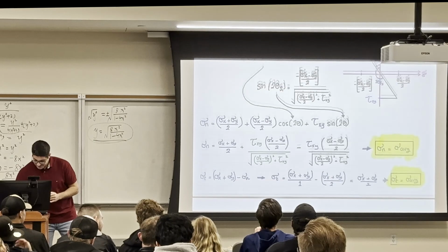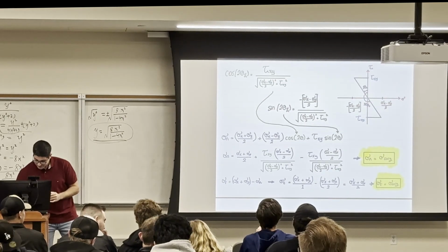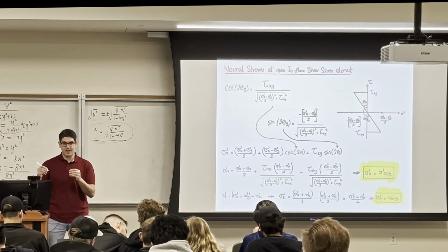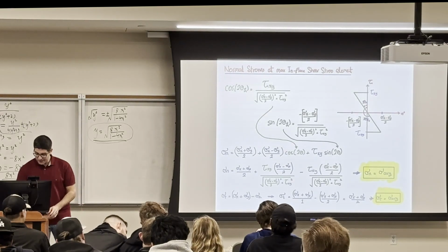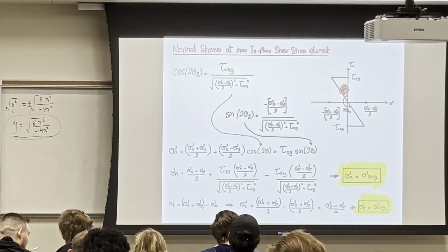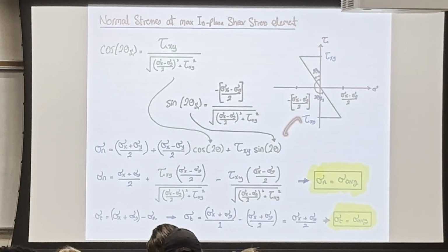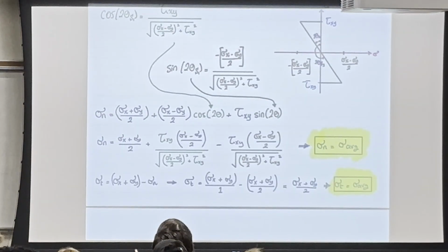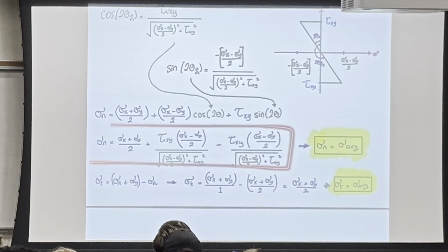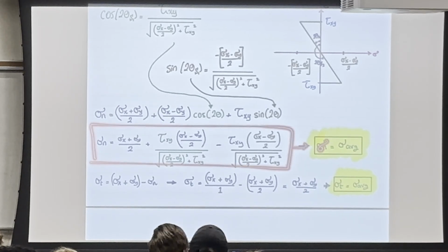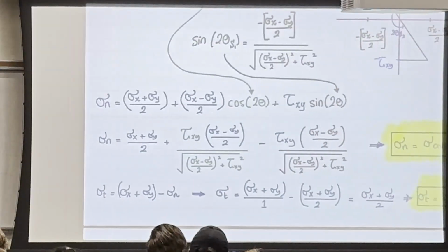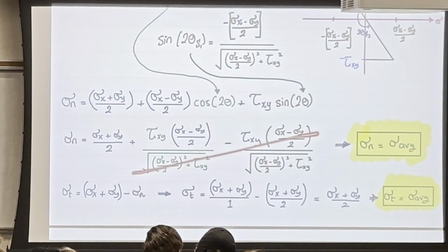So here, I just took the theta, and instead of substituting the theta, because I want to generalize this, I took the cosine of the theta s and substituted in the sigma n equation, because that's the only equation that I know with which, for any given theta, I can find the stresses. And if you did this, you're going to find that sigma n was equal to sigma average, which is, if I substituted, you're going to see that these two terms cancel each other.